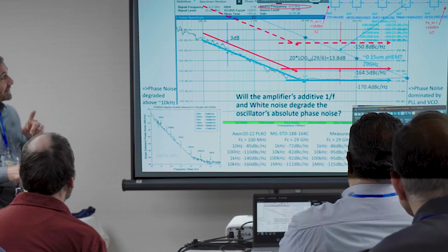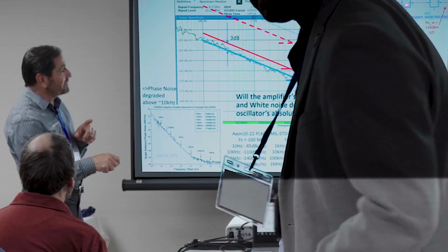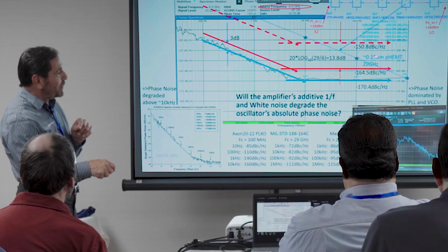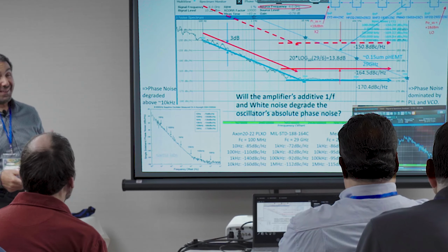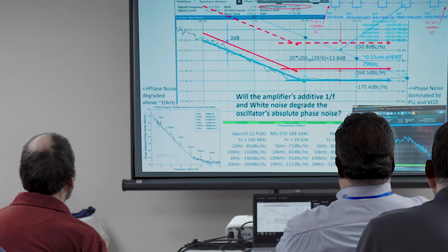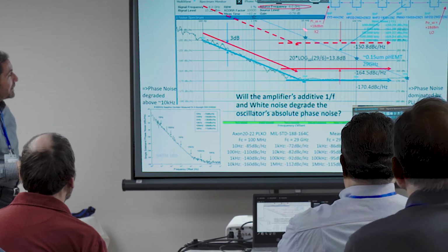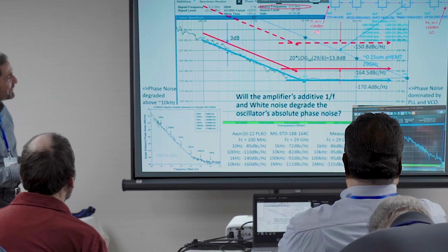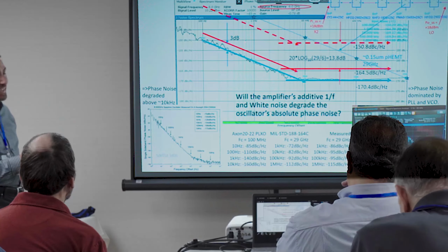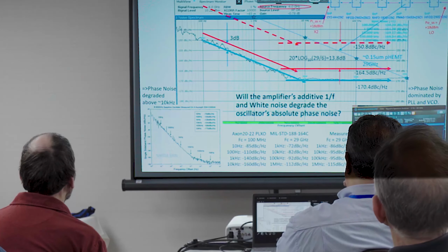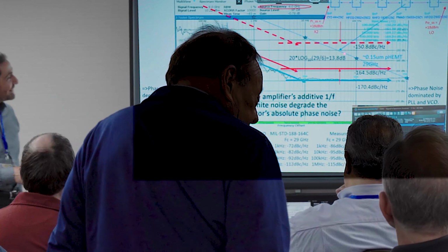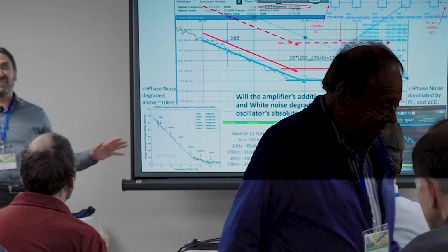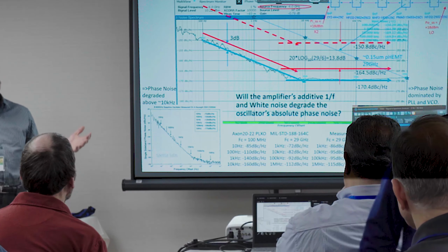But we forgot one thing. There's this preamp here. Happens to be a 0.15 micron preamp because I'm operating at almost 30 gigahertz. I'm kind of stuck with that type of gate length. Look at its 1/f noise. All right, I have to add these with power addition now. So I went through all this trouble of optimizing power levels and getting everything set perfectly, and this one guy comes along and kills everything. All right, but that's life, right?